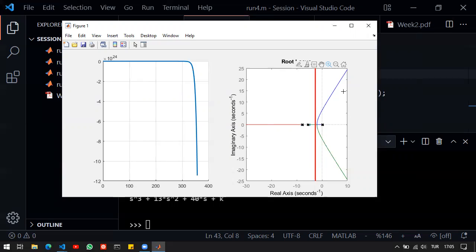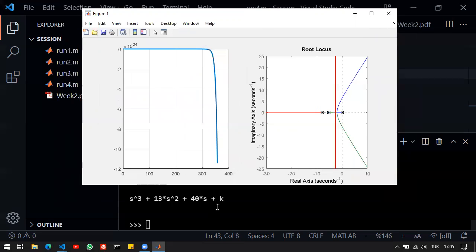It cannot do much because of this limitation. If you're free to choose all the coefficients of this polynomial, then you are basically able to do anything to this system: choose any rise time, settling time, overshoot whatsoever. But if you have just this constant term, then that's basically it.